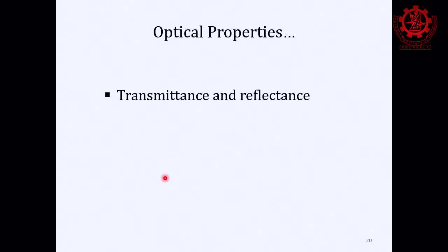So those are optical properties you can characterize in terms of transmittance and reflectance. What is the difference between transmittance and reflectance? How much light is passing through and how much light is reflecting. If too much light reflects, then what will happen? You will not see what is inside. It's like if it's a very glossy surface, then a lot of light reflects, so the surface itself appears shiny, but you don't see what is inside, right? So these are important depending upon what product you have inside, what kind of transmittance or reflectance you want on that surface based on the application of that packaging material.